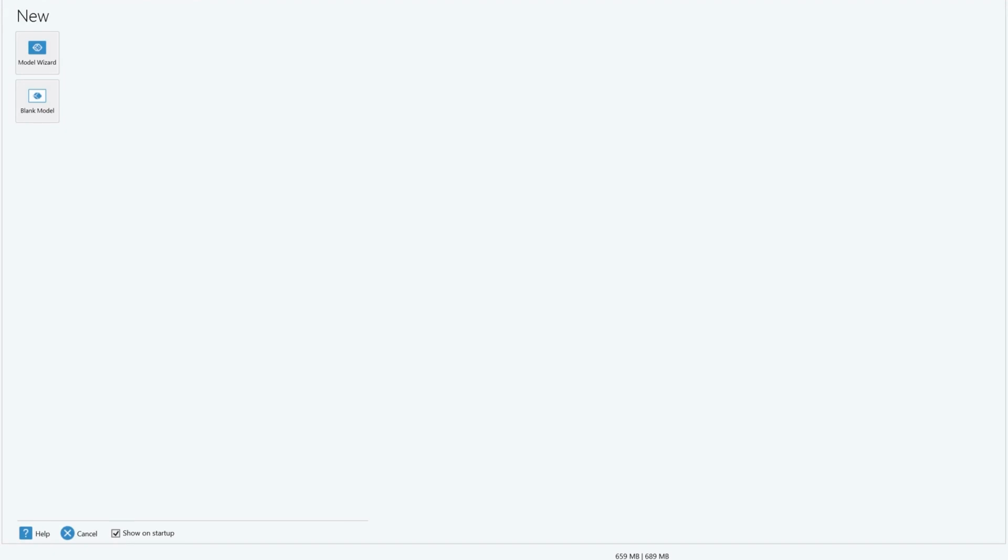Greetings everyone. In this video we will learn about how to design a model in COMSOL, export it and slice it in the software Ultimaker Cura for 3D printing. We begin with starting COMSOL, selecting Model Wizard and start working in 3D space dimension.